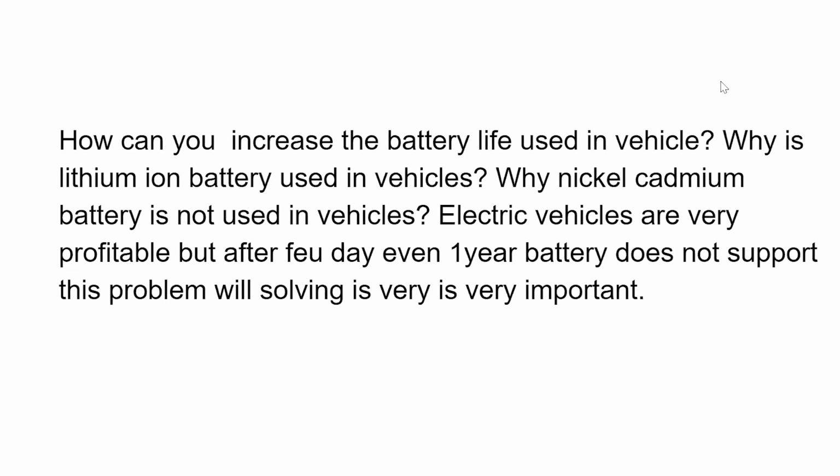The lithium ion battery is used because it has a higher voltage. If you take one individual cell of lithium ion and one individual cell of nickel cadmium, the lithium ion cell has a higher voltage compared to nickel cadmium, and that is why lithium ion is becoming more of a standard. If you pack more cells in a vehicle, you get a higher voltage, and if you get a higher voltage, you get higher electrical power. That is why lithium ion is, you can say, the future for batteries, unless something else comes up. But as of now, everybody is focusing on lithium ion batteries.